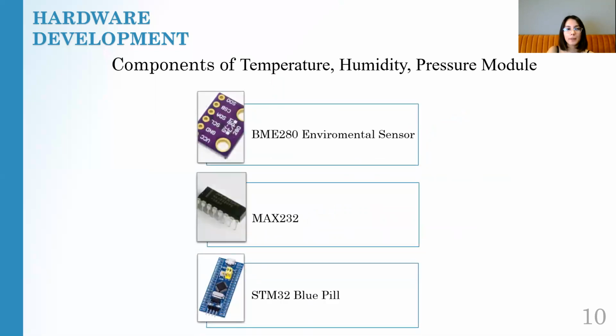And hardware development. In this study, it's also planned to develop a device that will detect the weather conditions of the environment while determining the indoor localization. This device will communicate with a gateway-enabled anchor that can be connected to Ethernet. Weather monitoring results will be sent from the device to the anchor via RS-232 with NMEA sentences. In this way, values of the environment, such as temperature, humidity, and pressure, can be monitored.